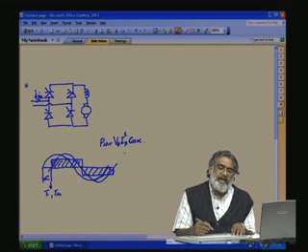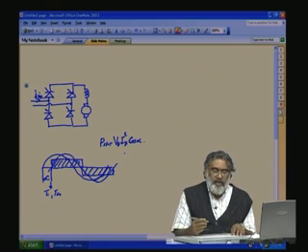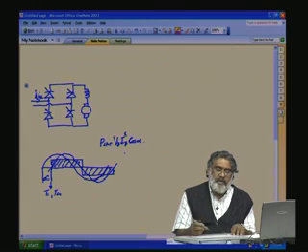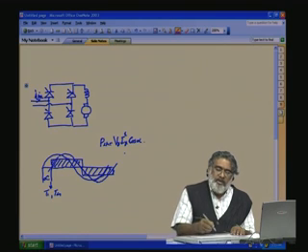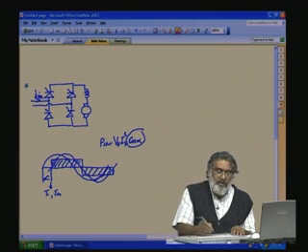So, in the ideal case, to draw the maximum power for a particular output voltage from the input, the displacement angle between the voltage and the fundamental current should be 0, so that the power factor should be unity. But in the phase controlled converter, what we found is cos alpha. Now, then we went for the semi controlled converter.